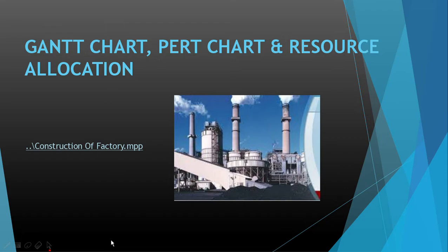Now this diagram tells about which activity follows what activity and in what order. And here we can see that with the finish of brickwork, we have 4 simultaneous activities which start, and flooring starts when brickwork and removal of support is done. This pink line denotes the critical path, whereas white activities show non-critical activities. So this PERT chart ends with site cleanup.